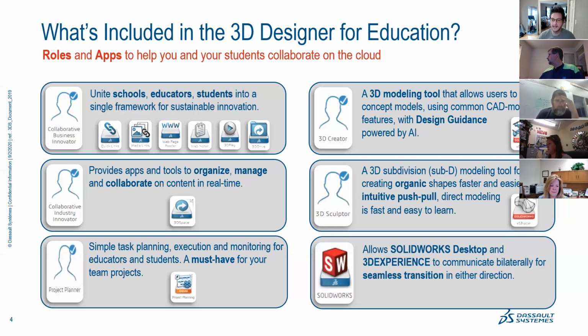But if you get back to the classroom and you want to use the cloud to bring the CAD files in to do a large assembly, you can do that. It's not a perfect transition. They're made on two different kernels, the platform and SOLIDWORKS. So you can bring the files in from SOLIDWORKS into the platform and use them just fine. But you won't have your full feature history that you would have inside SOLIDWORKS, because the part was natively made in SOLIDWORKS.